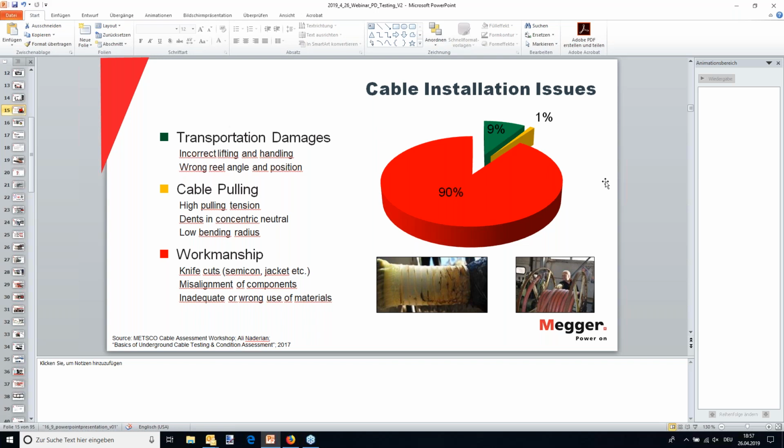There was a question related to assessment criteria, specifically focusing on PDEV versus PDIV, the importance of one measurement over the other. Well, the important measurement is the inception voltage. It should always be above U naught. That is one of the main things that splits what is critical, which is at operating voltage and below, and per definition not so critical, which is above operating voltage.